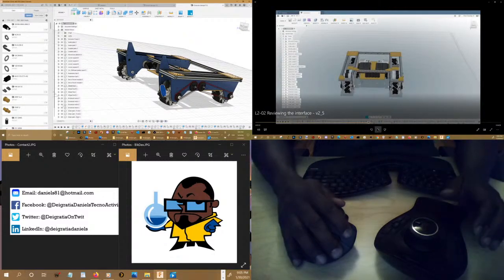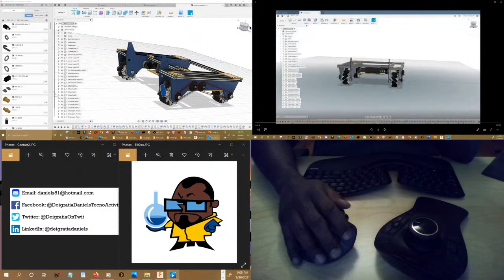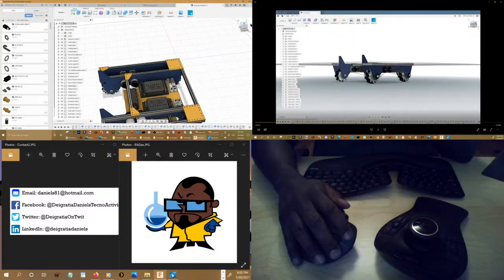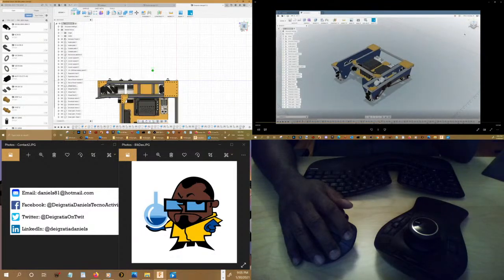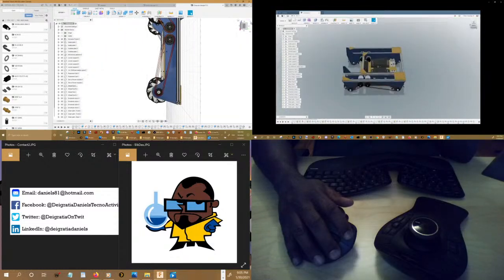Okay, watching more of the video. Using 2 fingers to pan, pinch gestures to zoom, and holding the shift key and using 2 fingers for orbit. In the upper right of the interface is the view key. Clicking on the face, so they call this a view key, changes the point of view. You can also click and drag directly on the view to orbit.